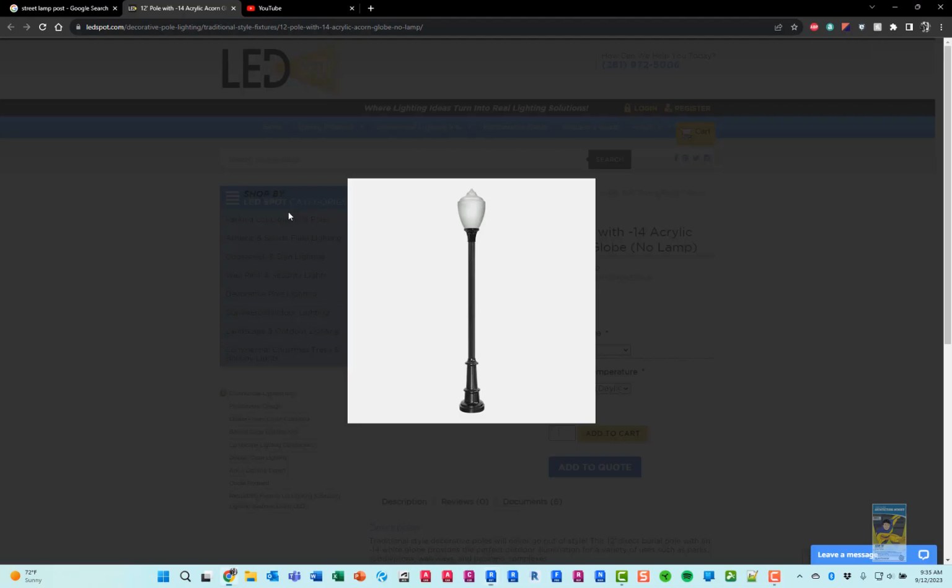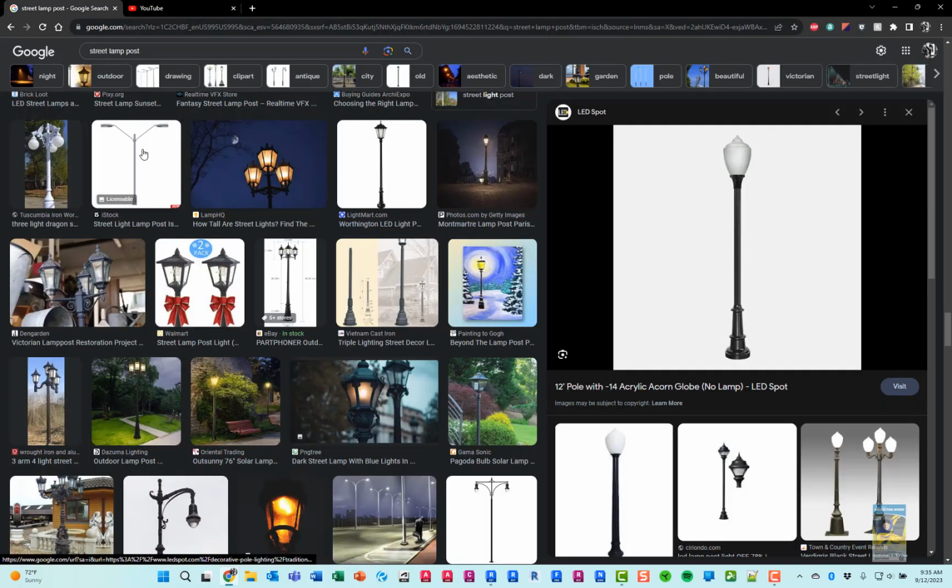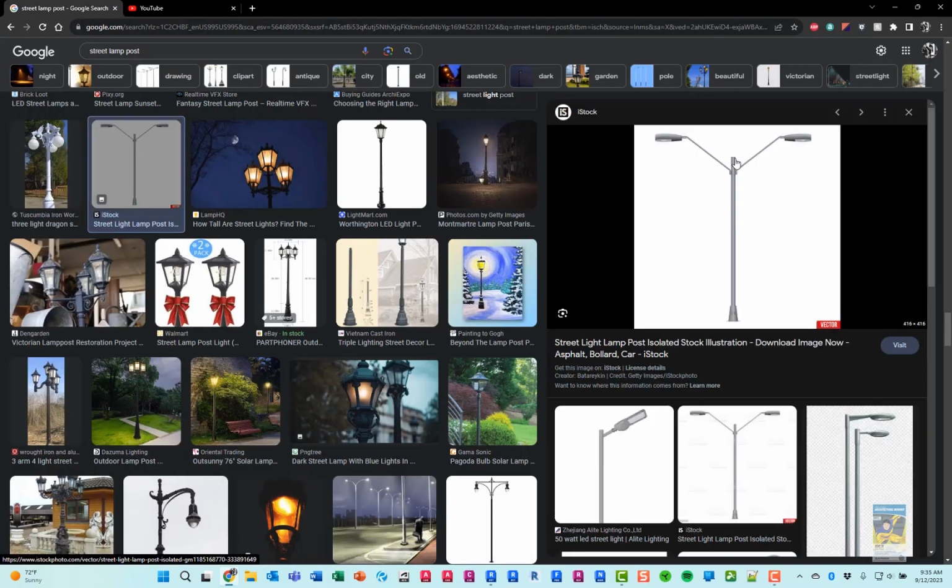But if you were to go back and do other street lamp post families that can be complicated like this one, it's the same premise. Build your vertical structure, build your housing and everything as a single family that's a host family. Then if you want to, you can build this housing and the light source as another family and nest it into this main housing family, and then copy it, rotate it and everything, and align and lock it where you need it to be, and then give this a vertical height.